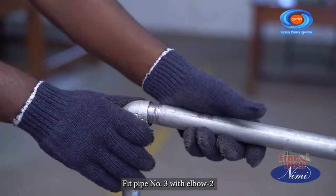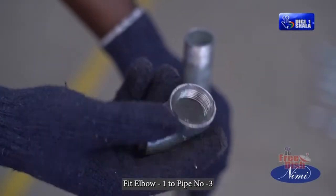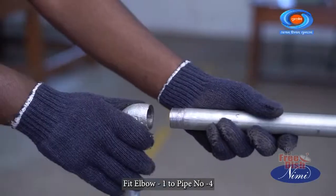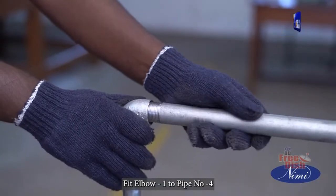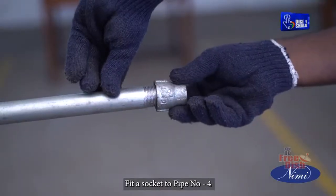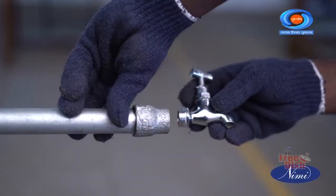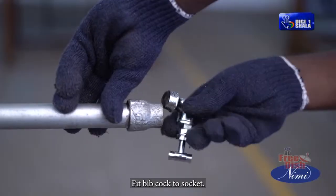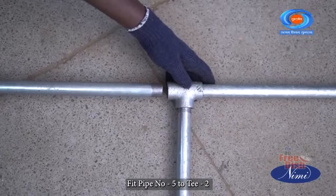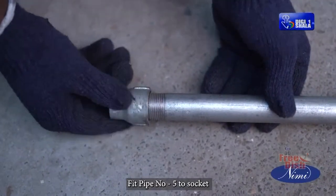Fit pipe number 3 with elbow 2. Fit elbow 1 to pipe number 3. Fit elbow 1 to pipe number 4. Fit a socket to pipe number 4. Fit bibcock to socket. Fit pipe number 5 to T2. Fit pipe number 5 to socket.